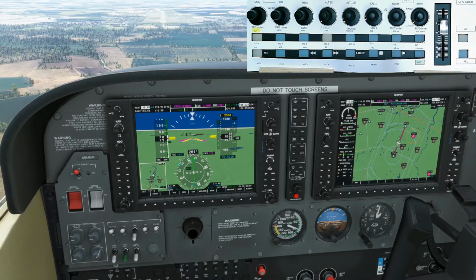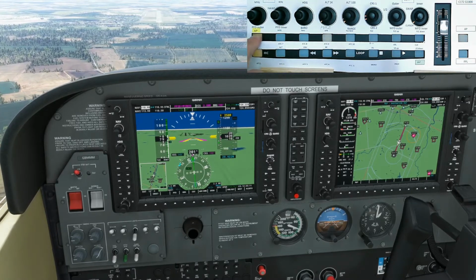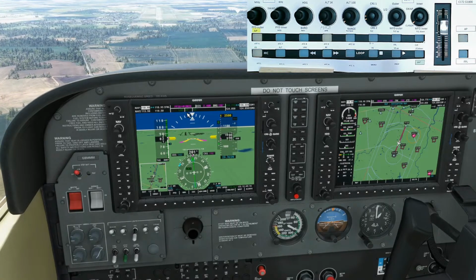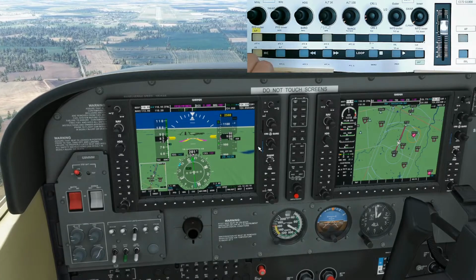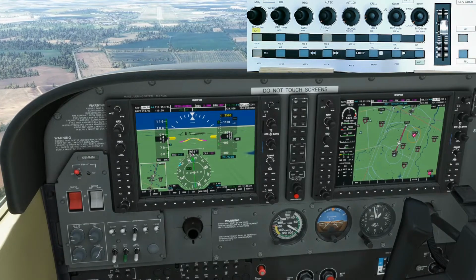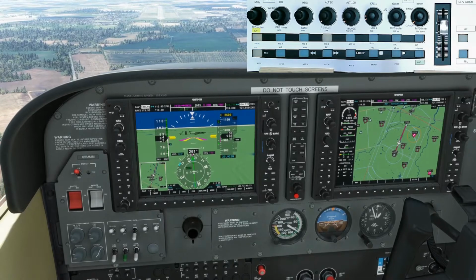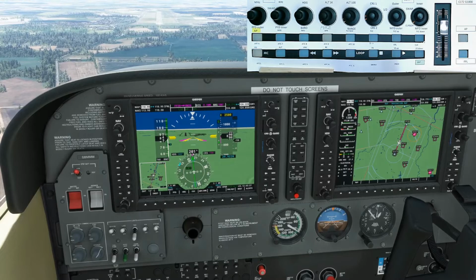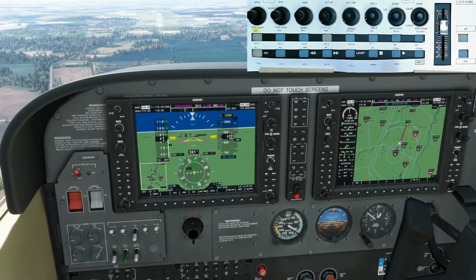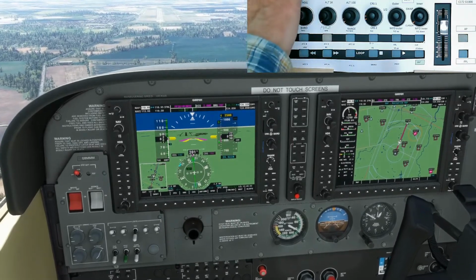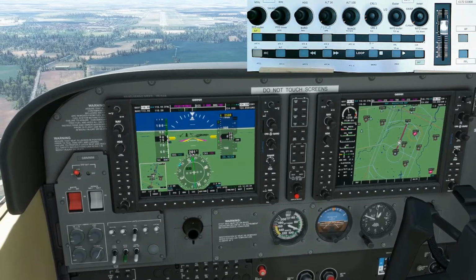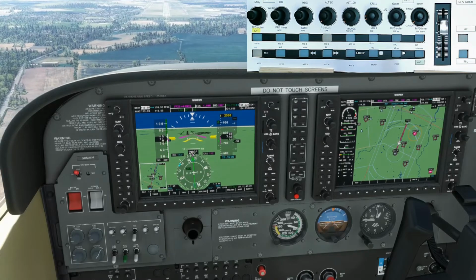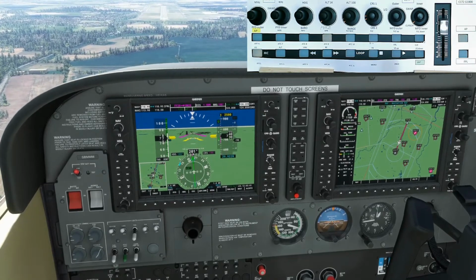If you remember, there's a bit of a bug with the autopilot. If I press the button here, the light will go out here, definitely disengage, but it will still be saying the autopilot's on here. We can't find out how to get that indicator to go away, but you should hear the chime. Let's watch that throttle getting a bit fast. Let's bring one more layer of flaps in, stabilize that, and take the autopilot out. Autopilot's now out, and it's in my own capable hands.